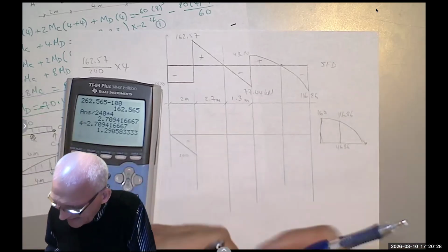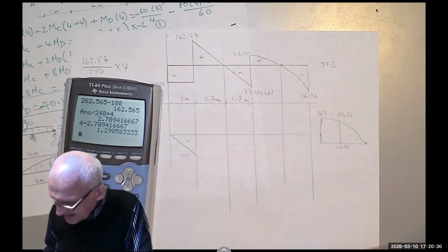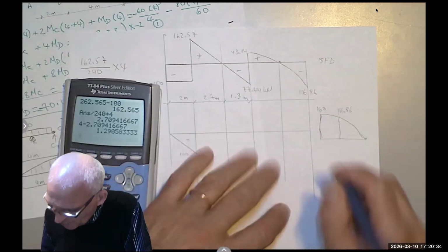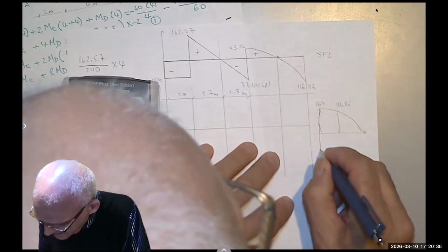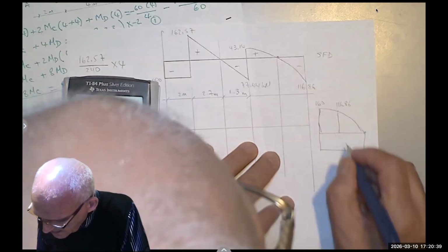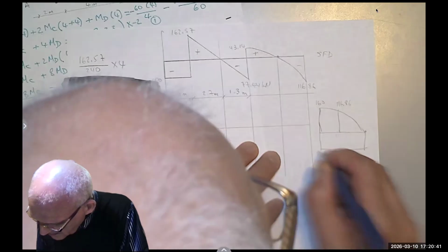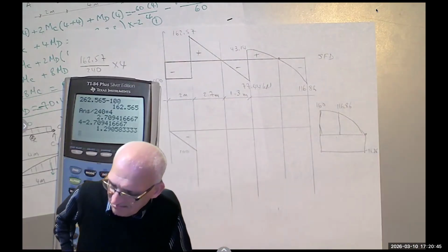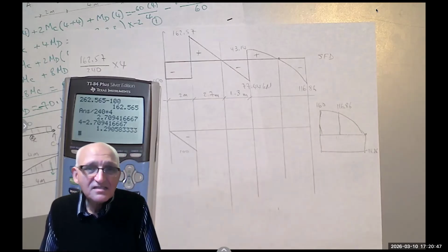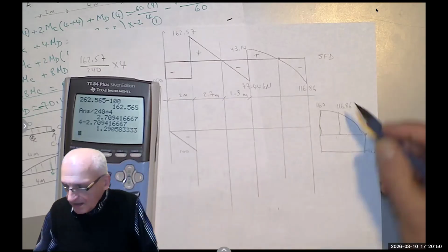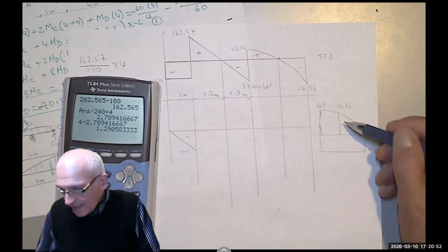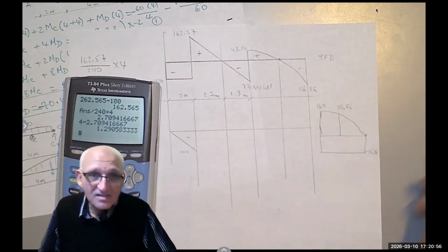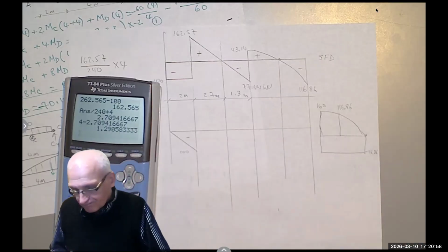But notice, if I added 116.86, I have to subtract 116.86. You might say, but I still didn't get the distance. Easy. This square over that square is this over that, because it's a second degree parabola.